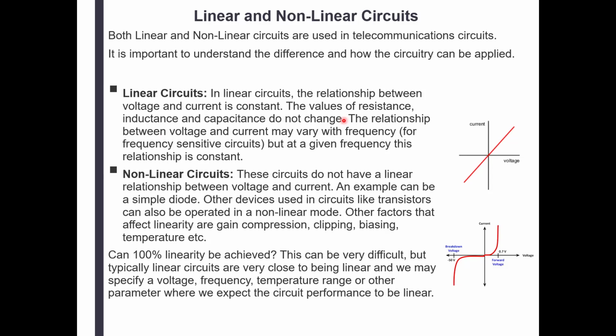A reactive component is, for example, a capacitor or a coil or inductor. They are going to behave in a different way if a different frequency is applied. So things will change. But as long as the frequency stays, you change the voltage, the current changes, and then again, you're going to get a straight line.